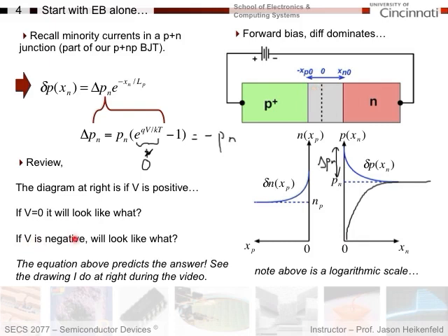And for a reverse bias diode, we know that at the depletion edge, every hole that's created as a minority carrier hole on this side will wiggle around, fall off the cliff edge, and go to the other side. Only until you go further away do you see holes that are created that won't go too close to the cliff edge and fall off to the other side as drift current. So again, this is a little bit of review, and it'll be important for understanding both the emitter base and the base collector side of the BJT.